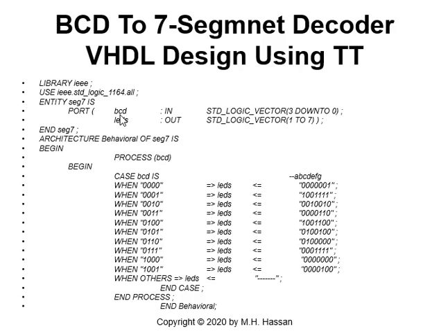It is WXYZ. If you define it as BCD, binary coded decimal, you can define it as a 4-bit vector. So this is an input port in standard logic vector 3 down to 0. It means we have BCD(3), BCD(2), BCD(1) and BCD(0).